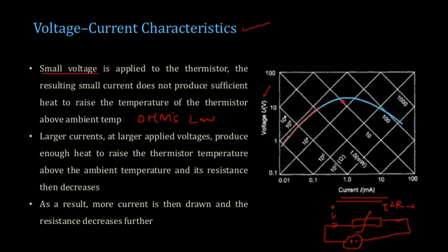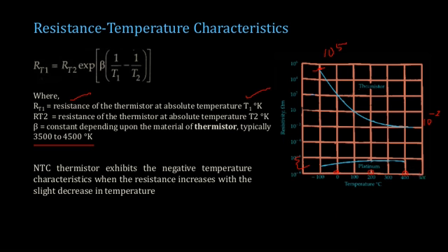So current is increasing and resistance is reducing, and your voltage increases and then drops, and the current will continue to increase. It is not that current increases infinitely. The current will continue to increase as long as there is a change in resistance, and after some time the resistance will settle to some particular value.